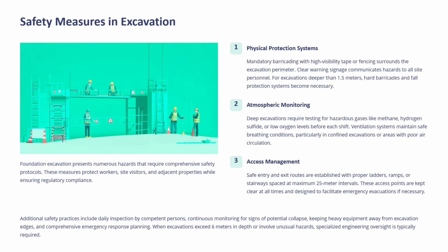For access management, you have to make certain arrangements. Safe entry and exit routes are established with proper ladders, ramps, or stairways spaced at a maximum of 25-meter intervals. These access points are kept clear at all times and are designed to facilitate emergency evacuations if necessary.